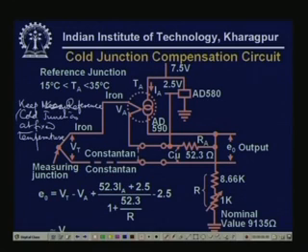So that's cumbersome. Therefore what people try is this: the voltage drop which occurs due to the ambient, suppose you keep the reference junction in the open, so the ambient temperature is going to vary, and that will cause some error. So what you should do is compensate for the ambient temperature variation using electronics, by measuring the ambient temperature variation. That's the smart way to do things, which is also much easier.